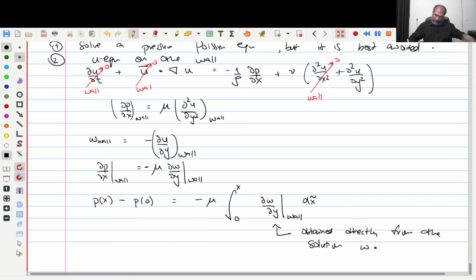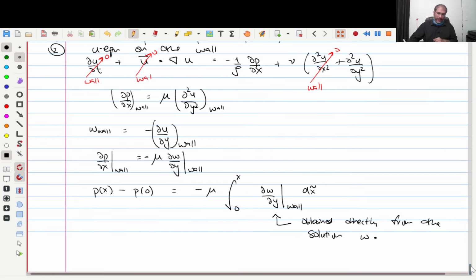Okay, so just a note here about when you'll be calculating the pressure values. Now pressure for an incompressible flow situation is always relative. So as we did for the stream function, we can make the pressure value a fixed reference value at some point, and then everything else is in reference to that pressure value. So typically we'll sometimes say that at the outlet the pressure value is P equal to 0, and then everything else is in relation to that. But that's again an arbitrary choice. You can choose any pressure value to be a reference pressure value.